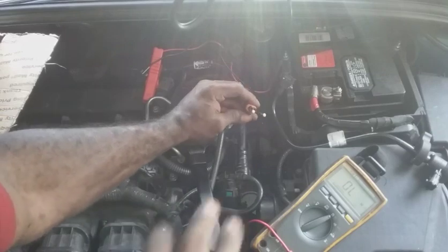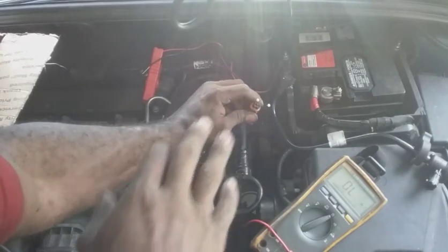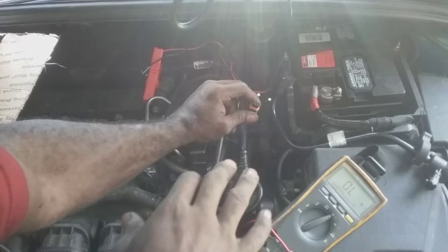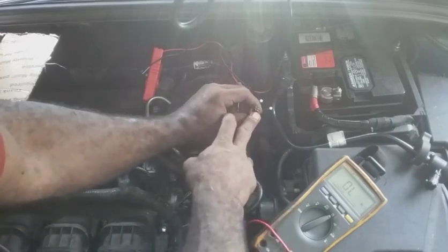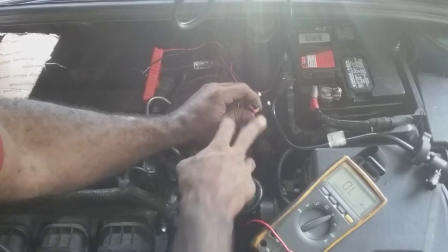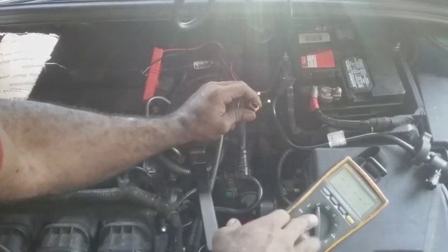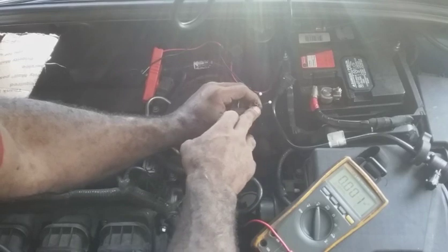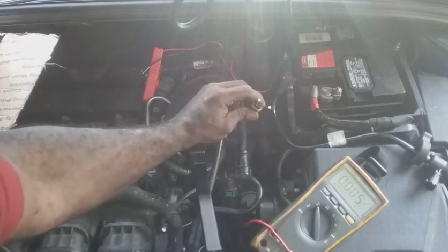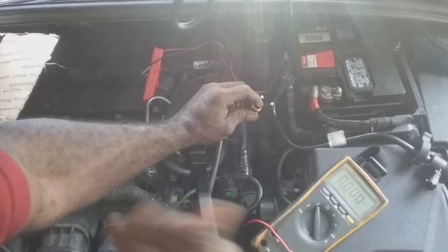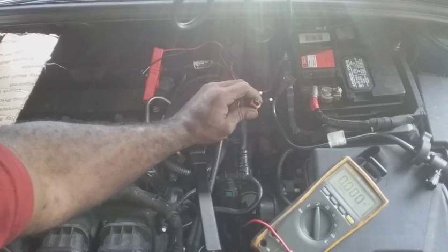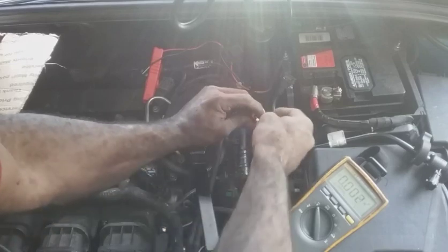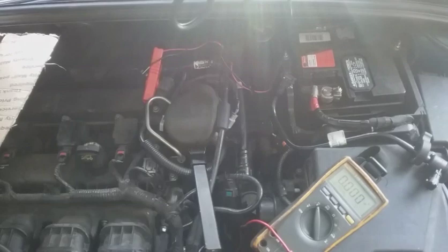So to go back before I go run and get my part, the basic test for this to answer if there's a complete circuit here, being that we know there's going to be resistance on the switching side, is connect the voltmeter to both pins and see if you get a voltage value. Again, it's going to be low because there's resistance on the side. It's not a straight up ground or low ohms. So therefore we're going to have a voltage, but it'll be low. That doesn't indicate there's a problem. It just indicates that this is a switching circuit, therefore the low voltage.